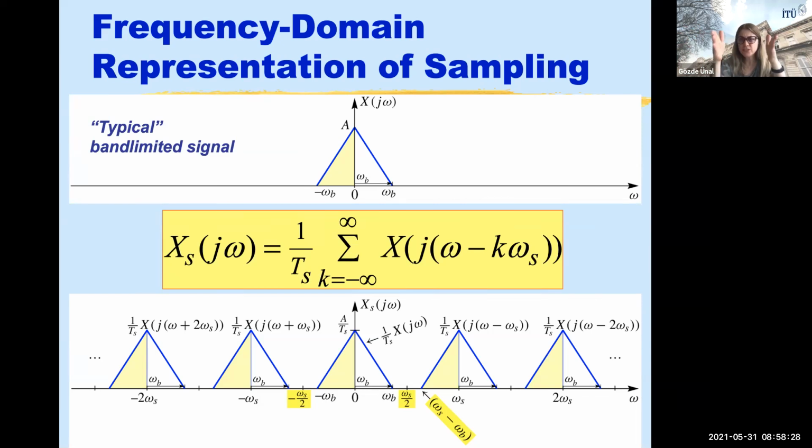Think of this as our classical example. We digitized our song, for instance. You are in a concert, you have a microphone, you digitize that song, store it, you can do some manipulation, but now you want to play it again, right? Now it's a discrete to continuous converter through a speaker. If you have overlapping replicas in your sampling, if you don't do your sampling correctly, you can't really replay the original sound, or song. I hope that's clear. Is that clear somehow?